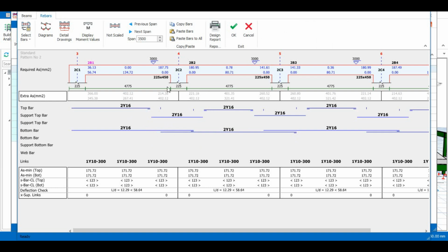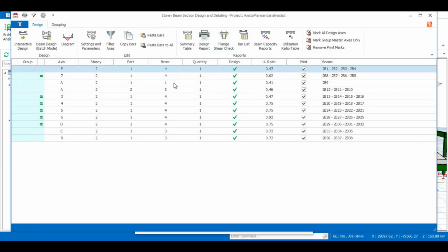It may tend to waste time, and when there's a better way to arrange your bars, why not just go for it? Once you are finished rearranging your bars manually for the beams, you could just press OK to activate what you have arranged. And if your design was marked red, it's going to be marked green once your design is OK.